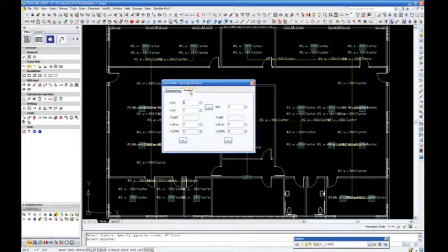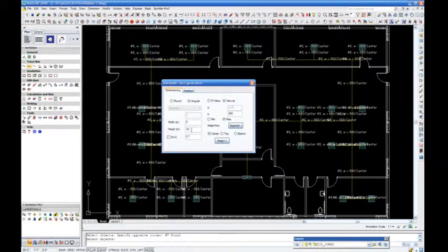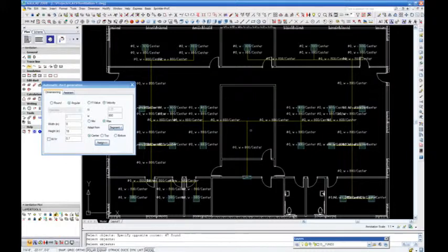The Automatic Duct Generator window has a tab to the right which is labeled Assistant. This is nothing more than a duct calculator. Now all the information is displayed in yellow as the round duct system. We will now select the ducts to be converted from round to rectangular. We will assign our rectangular duct height. We will use the defaulted 18-inch dimension.